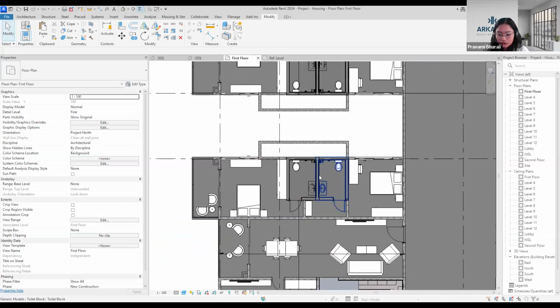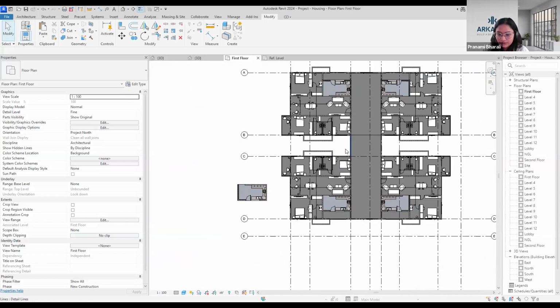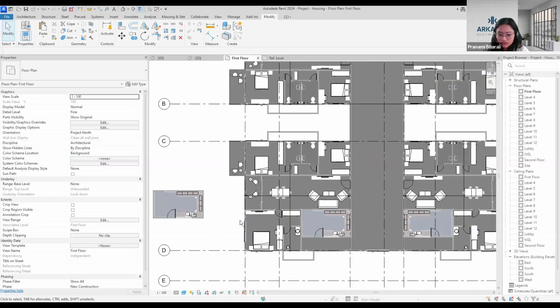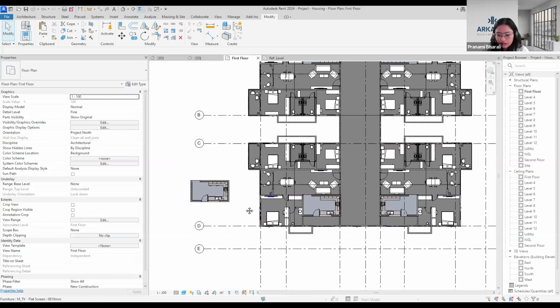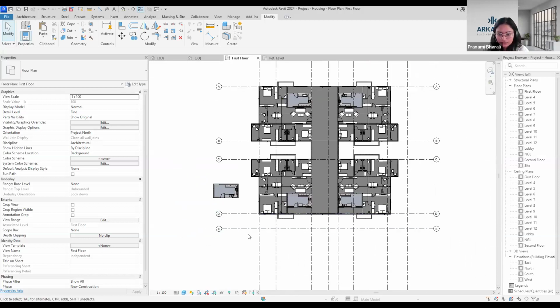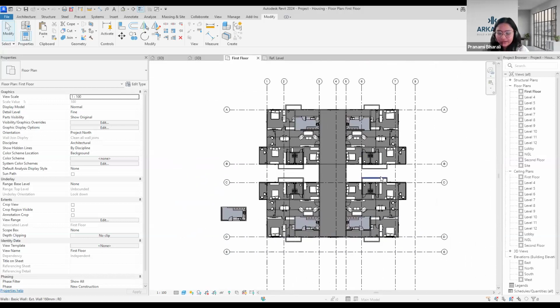There is no rule that the whole project should be on prefabrication. You can go for certain elements. For my case, you can see the elements where toilet block, the kitchen block, even the balconies you can do the same. Maybe the bedroom area you will not go for prefabrication, you will design that. So depending upon that you can decide how much percentage you want to achieve by prefabrication. That is up to you, and of course the design is yours accordingly.